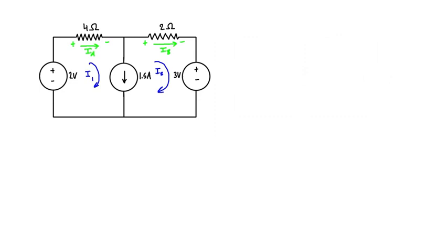What we can get from this diagram, first of all, is the relationship between I1 and I2. I1 is going around the loop this way, and when you come through this area, I1 is going like this, and I2 is doing the opposite. I2 is going up like that. Now we know that there's 1.5 amps going down. So I1 minus I2 is going to be the net, which is 1.5 amps. So we can write that down: I1 minus I2 is equal to 1.5 amps.